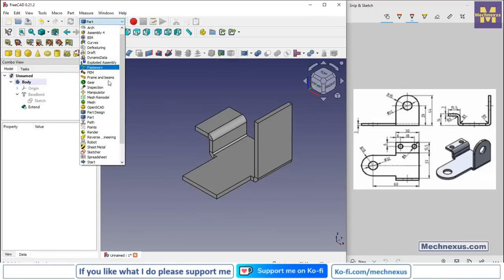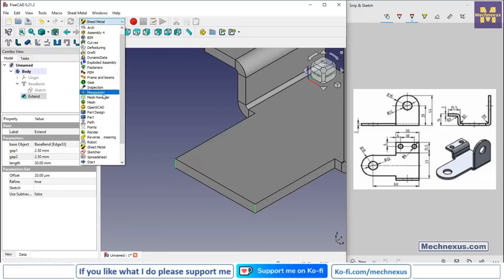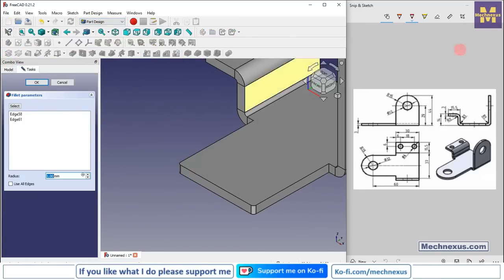Now we will switch to the Sheet Metal Workbench, and now we will provide this fillet of R15. I will select this edge and press Ctrl and select these two edges, and to give the fillet we will switch to the Part Design and click on the fillet, and here we will provide a fillet of 14.99.